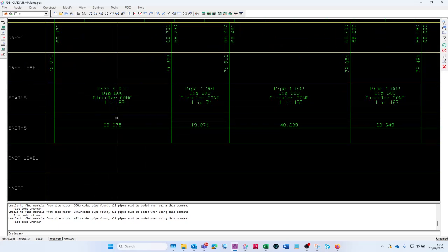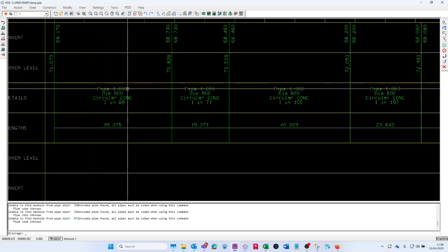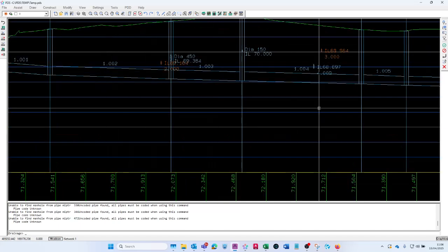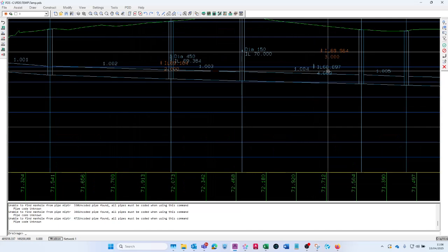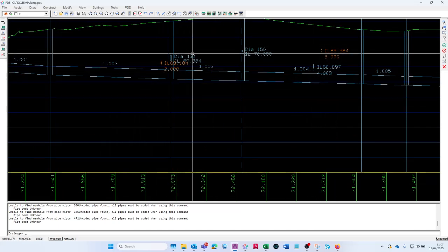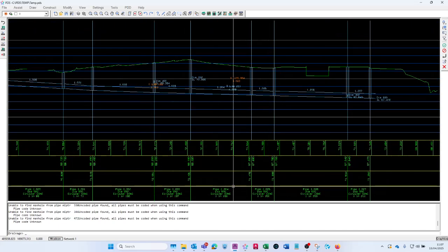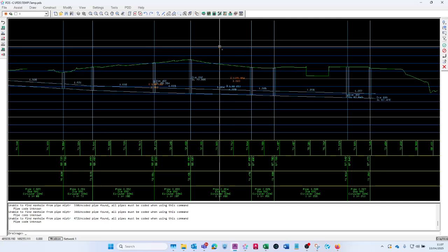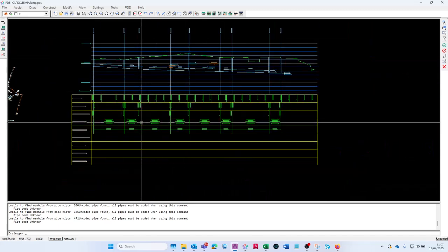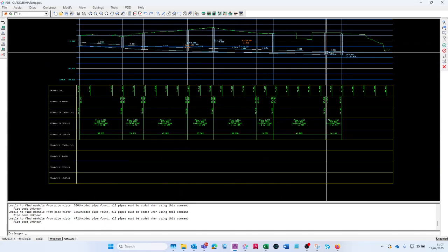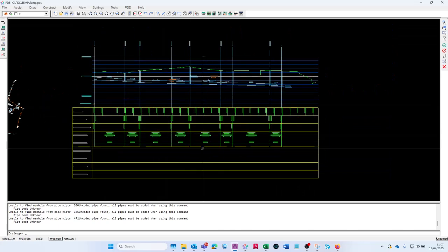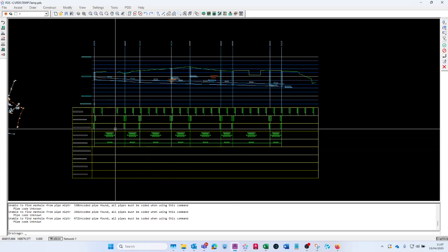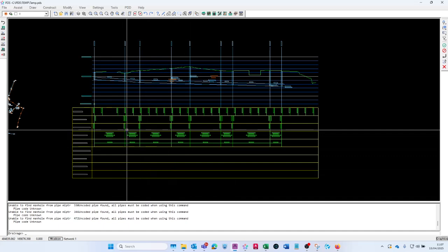And if you look here, now you have the pipe code. So you have the pipe code at the very top here, and then adjacent pipe. And here you can see sometimes it can get a bit cluttered. So I must admit, I always just leave it in the pipe detail section, not in the adjacent pipe. And if you do show the adjacent drainage within a corridor, this will get even more cluttered. So you have the space there, so you might as well just show it and make this less cluttered. So that's how you generate the profile. That's how you regenerate it to show, maybe change information on it and to update that information.